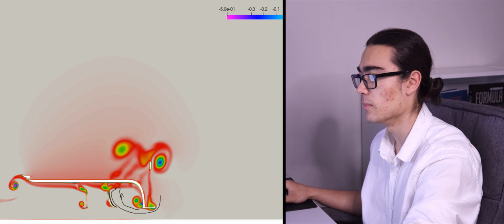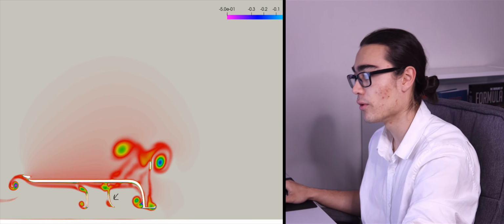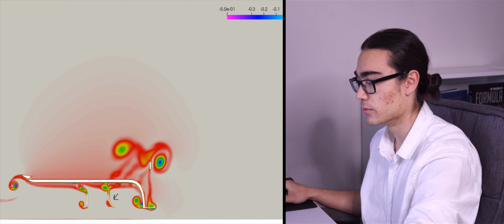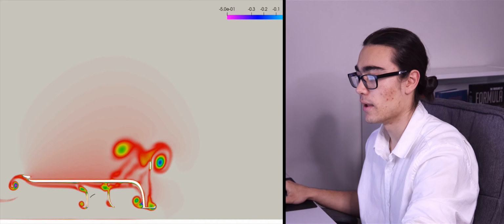So by curving that, you can minimize your losses from it, because the point of this strake is really a supporting role to manage this loss as it blows into the front tire, and not to spill inboard too much. This strake, on the other hand, is very different.